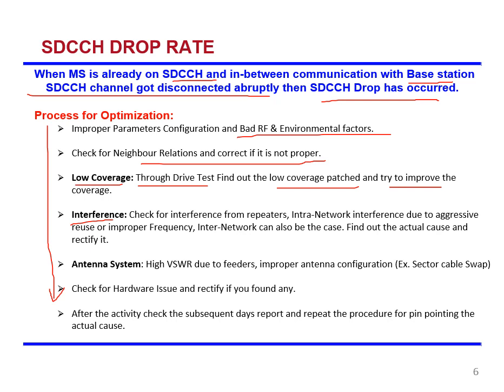Interference. If interference is more, if the noise is more, the signal to noise ratio SNR will be down. Quality of service will be down. Drops may be there. How to reduce the interference? The only thing is to reduce the frequency interference, co-channel interference, adjacent-channel interference.